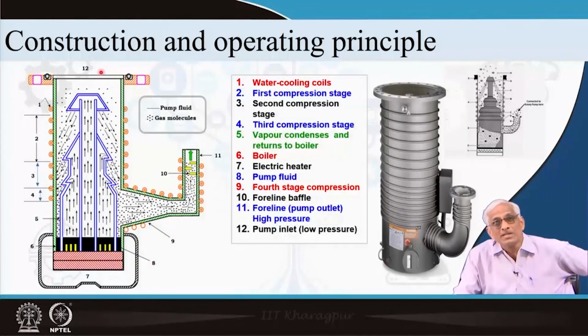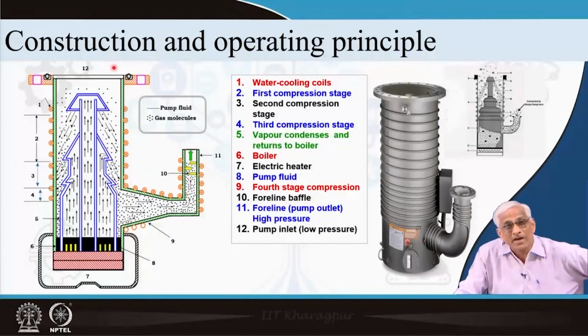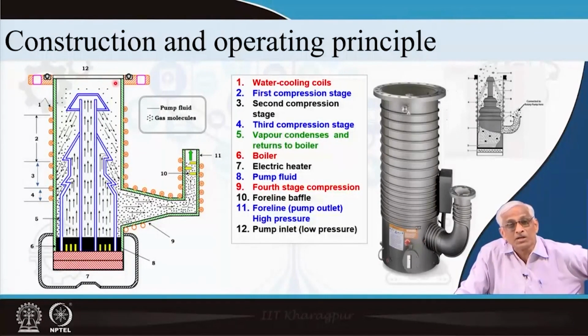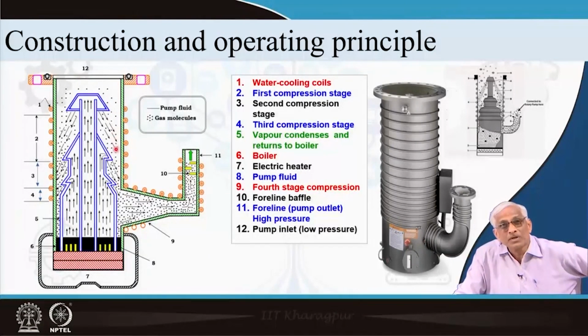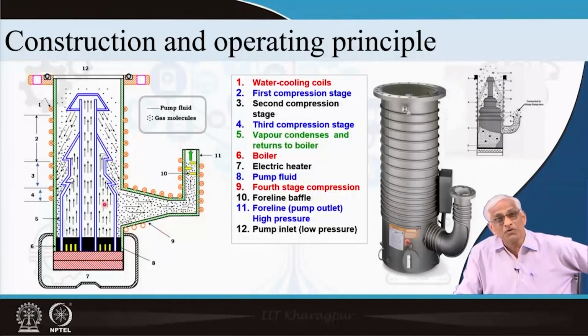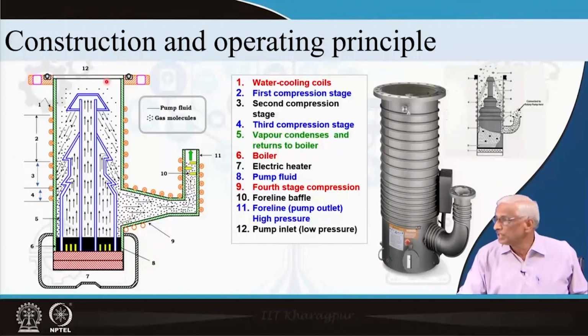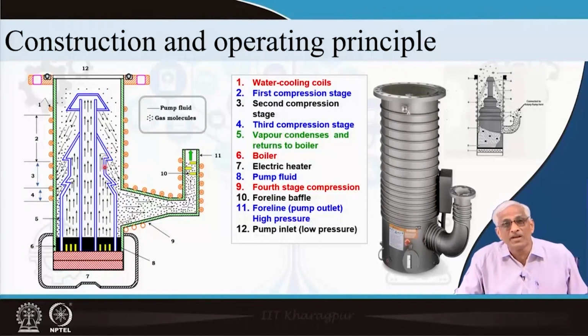Right now, imagine the gas has been already evacuated. In our case, air has been evacuated by the rotary pump to a level where the gas has started behaving like molecules, and the diffusion pump chamber, along with the jet and all, is also evacuated by the same backing pump, as well as the main chamber in which you are doing some application, whether it is a thin film or electronic. If so, what is going to happen finally?